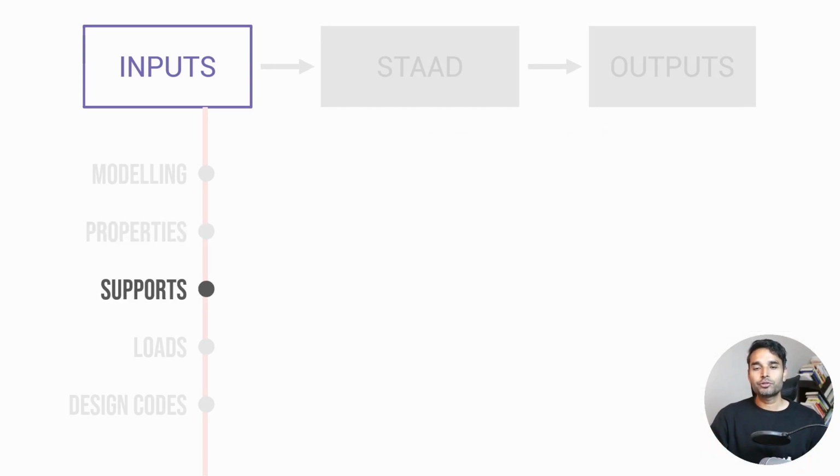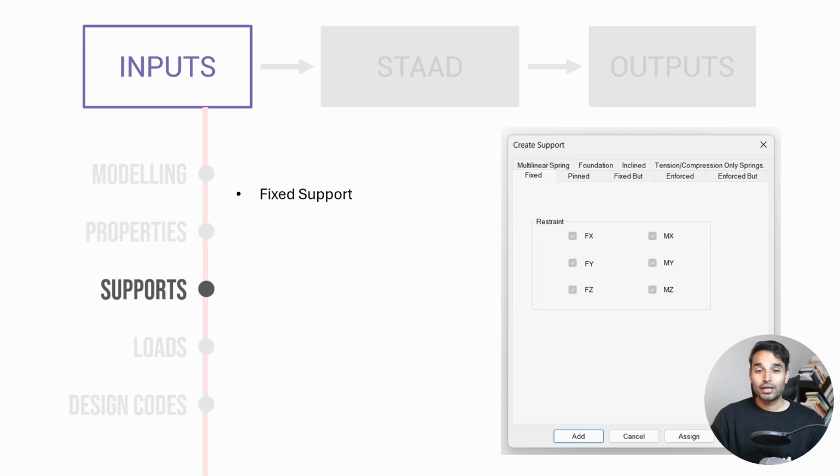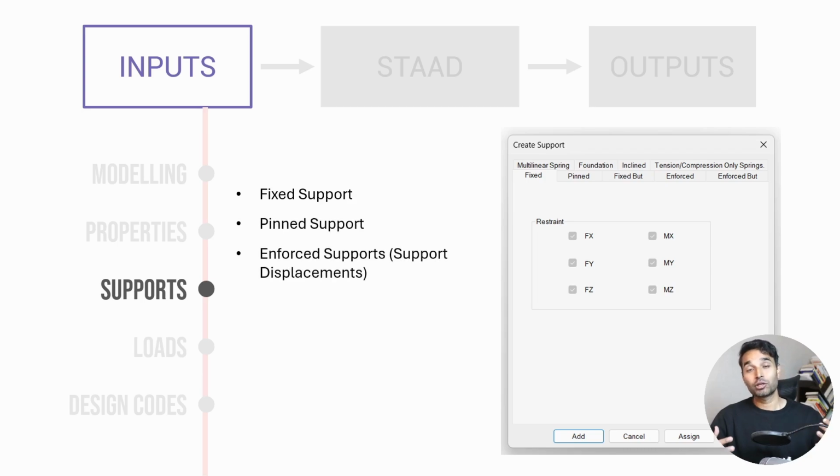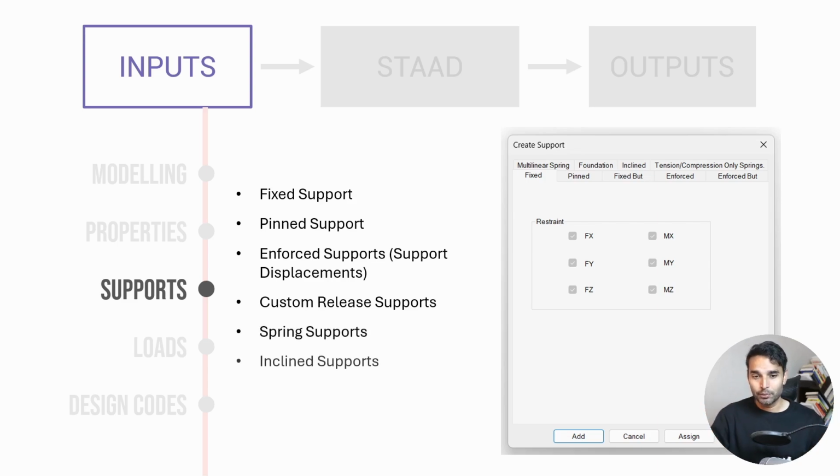When it comes to supports, STAAD is again extraordinary. It has fixed supports, it has pinned supports, it has enforced supports, which are basically supports that undergo a little bit of deformation or displacement. We have custom releases, so you can release moments or release reactions in one or the other direction. You can have spring supports, you can have inclined supports, you can have foundation supports. Every support which you can think of will be covered under STAAD.